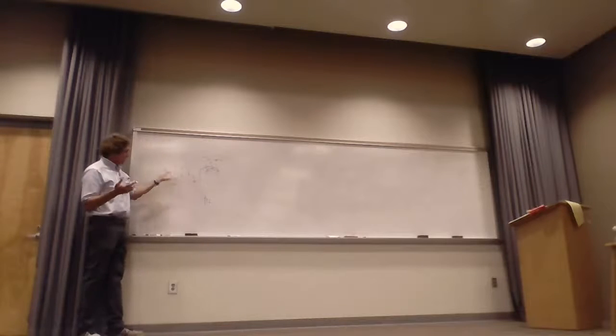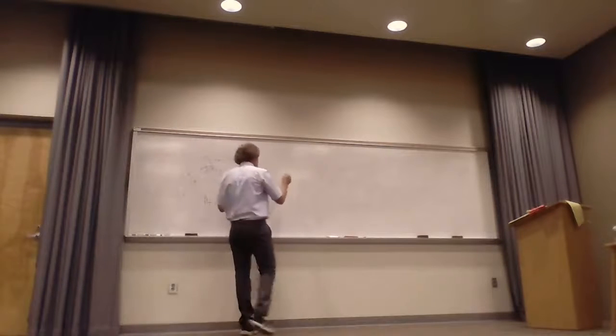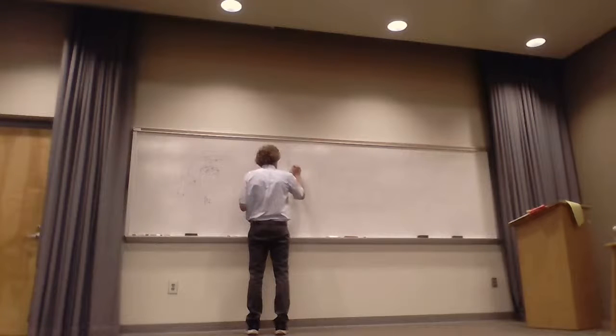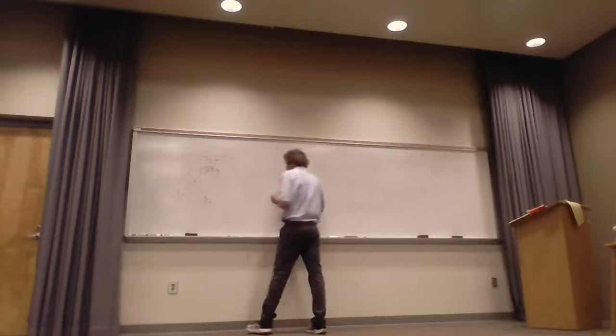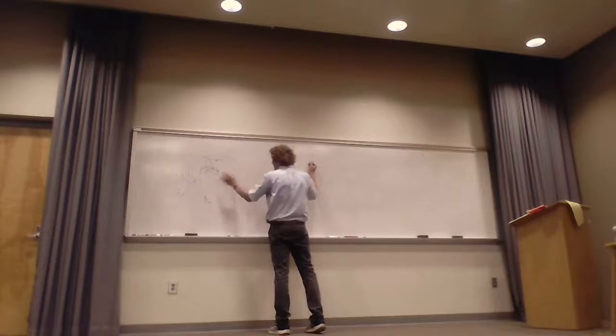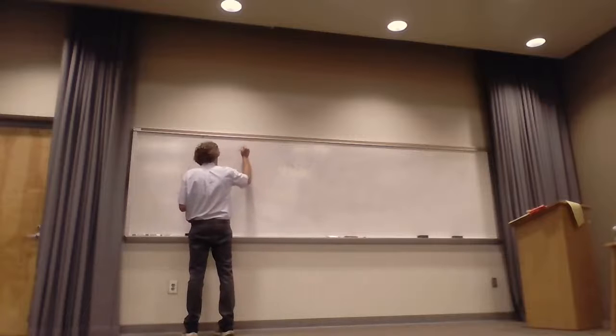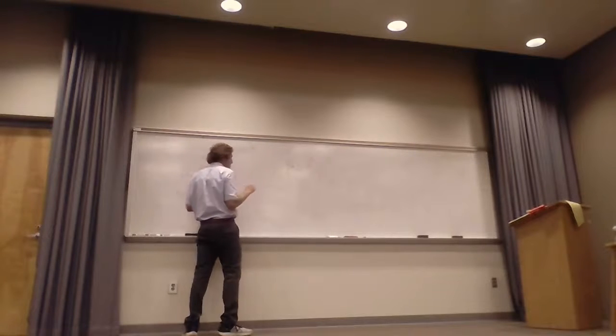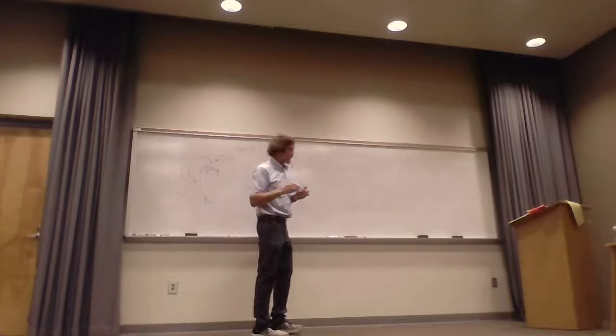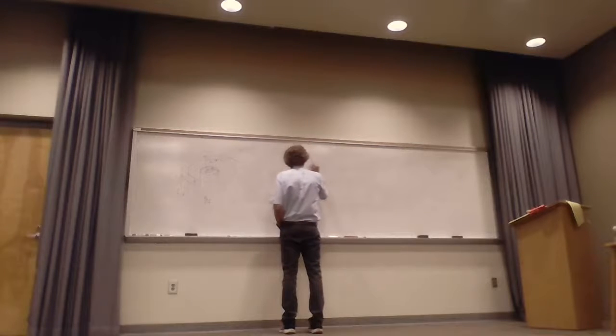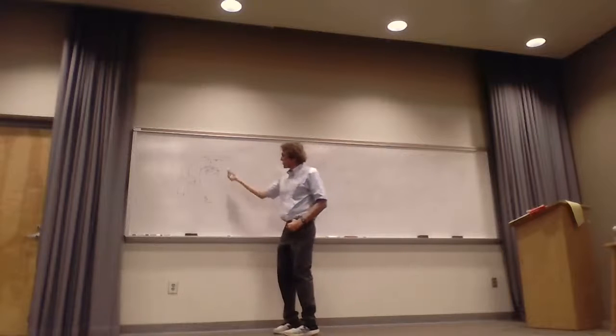If this was different, then we'd have to use a different conductivity here and here. Y'all with me? So we would say the resistance per meter, R per meter, would be equal, well, the resistance of the inner one per meter, the length would be 1, over sigma, and we're going to assume the skin depth is much less than radius A. So in other words, it's just a little bit. Now that's going to be over 2 pi A skin depth. That would be the resistance of the inner core.